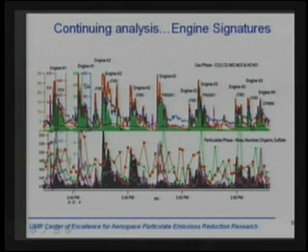Black carbon higher, number count lower. These are older technology engines. He was comparing older CFM56s to newer CFM56s. Here we're looking at JT8D, which is a different manufacturer's engine. But when we look at newer technology engines, irrespective of the manufacturer, the black carbon is lower, and the number count is higher. And so that actually highlights an important issue here in terms of trying to understand their impacts and what effects changing technology might have. Decreasing one thing may increase another, and so if one just worries about mass, one isn't getting the whole picture of what's going on with the particle emissions, especially from aircraft engines.